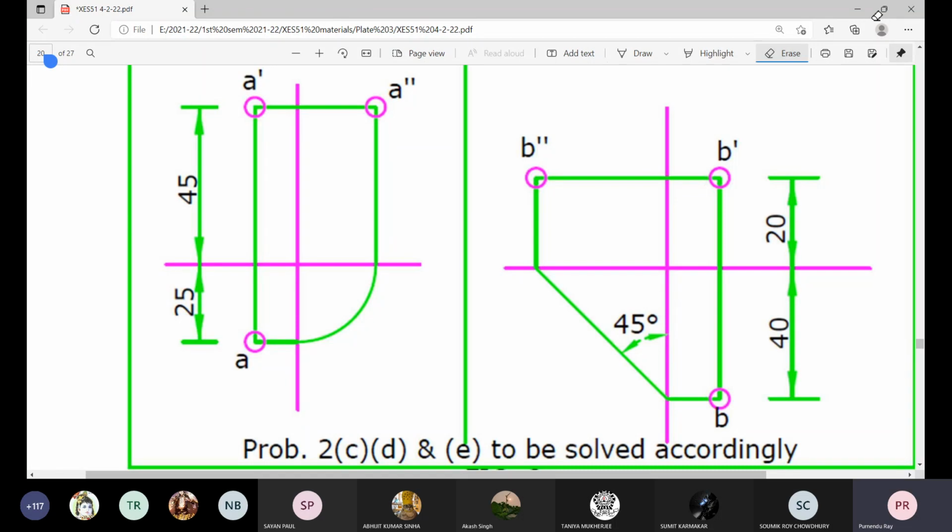Now, as this distance from the vertical plane to be indicated here, dv. So this is the method that we are making a quarter circular arc using this as center and this dv as radius. We are reaching to this location, so definitely this is also dv, and when you are drawing a perpendicular line, everywhere it will be at a distance of dv, that is 25, 25, 25, etc.